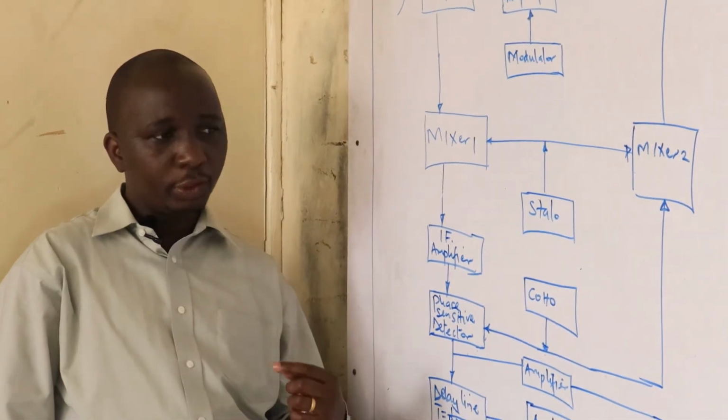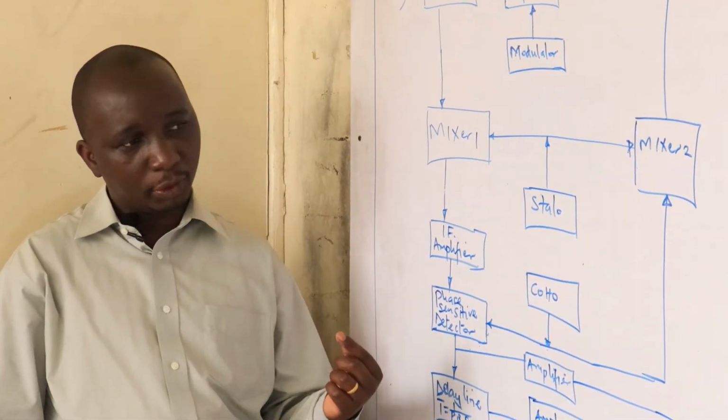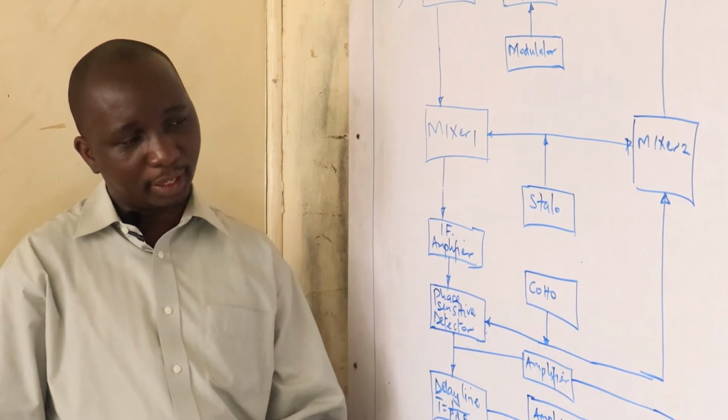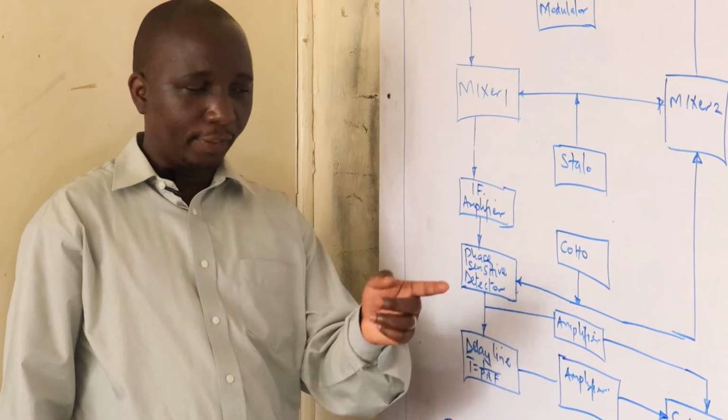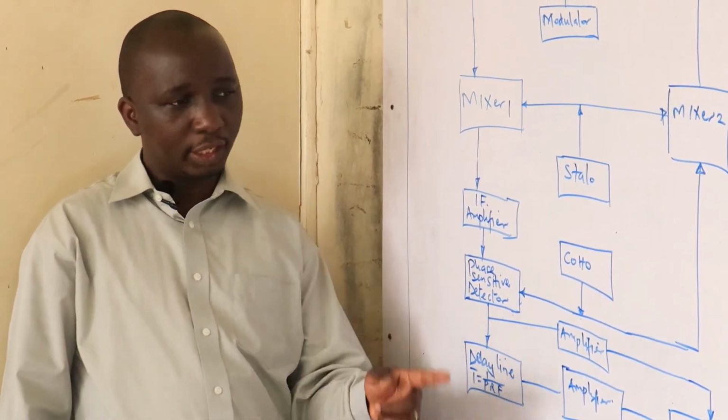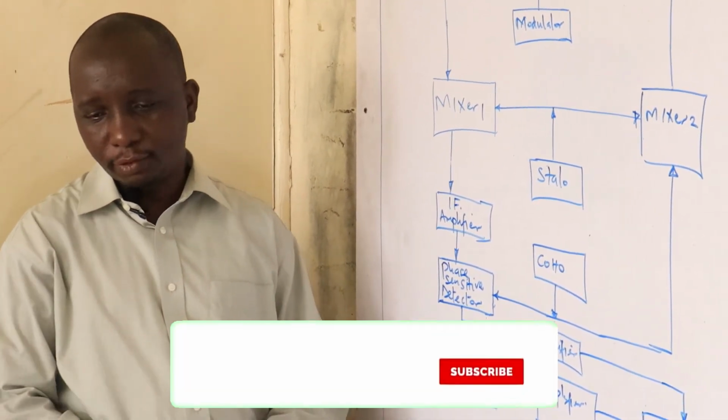So for us to be able to differentiate between one pulse and another successive pulse of similar character, we must be able to get a phase difference of 2 pi. And that one is only enabled in MTI radar using the blind speed principle. Then what is the blind speed?